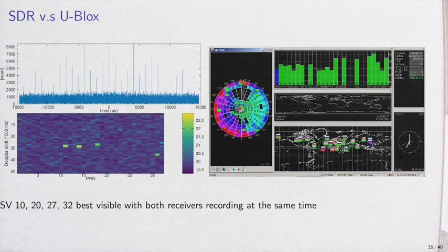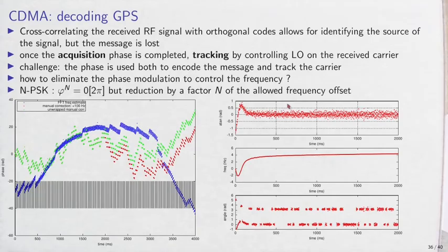So these are the charts that compare our output with u-blox's u-center output, and again you see here this correlation peak separated once every millisecond. This is the repetition of the correlations from the satellite messages that would allow us to recover the navigation data. These are consistent with the u-center output, and if you were to finish the acquisition step, then you can go for tracking, because you know that the satellite is not going to suddenly vanish from the sky.